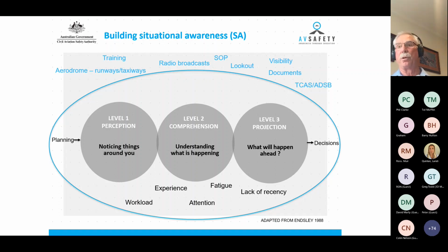If you've got an AWIS, you're able to determine a runway. By listening out early, you're able to hear what traffic is in there. The closer you get to the aerodrome, the more you're looking for aircraft, both radio and non-radio aircraft. At some of the country aerodromes, there's aircraft operating there that don't necessarily have a radio, and some might more or less not use it. And so all of those things come into your planning, and I'm not sure that a lot of places teach that particularly well, and that's something I think all flying schools should put a little bit more time and effort into, is giving students the tools to be able to establish that SA before you hit the circuit.